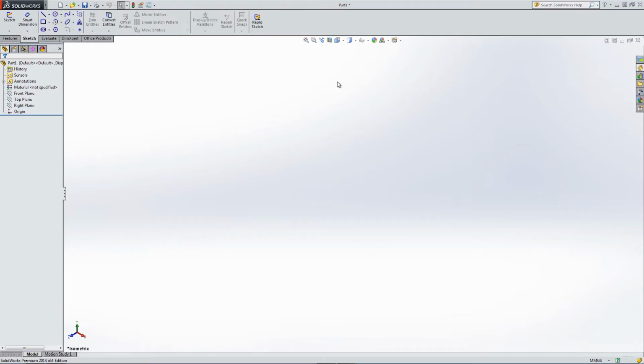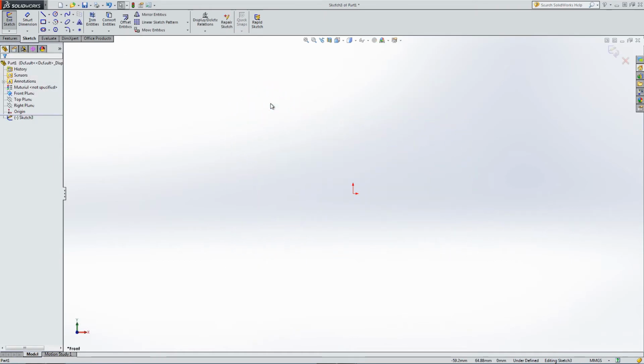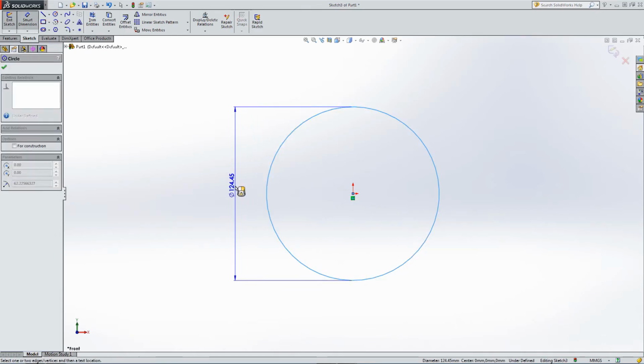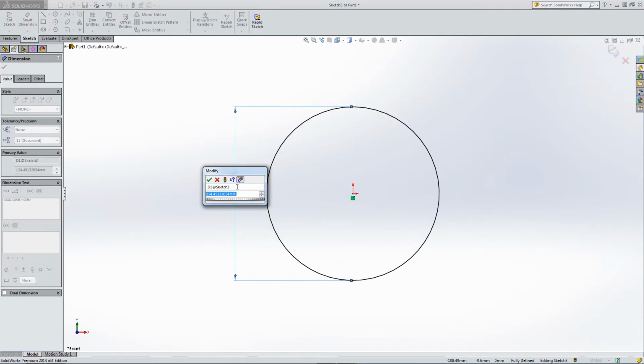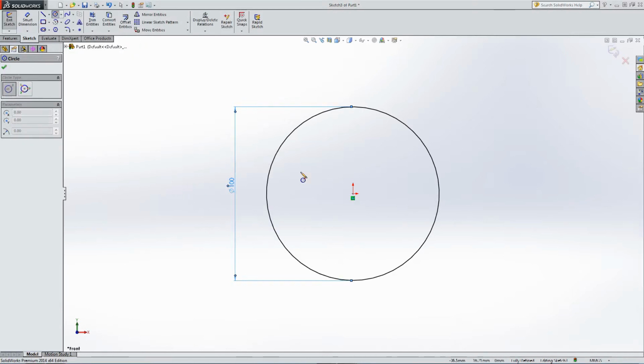In previous parts of this tutorial, we looked at the calculations and forming the involute on sheet form. Now we're going to start putting together an active working spur gear in CAD. So here I'm just drawing some of the critical circles that are going to form our shape. So this is the pitch circle I'm going to put in. Let's just give it an arbitrary figure. This is all going to change in a little while.